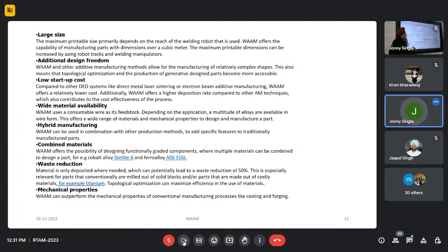But just imagine, analogous to this, you are going to now operate a facility with powder bed fusion. What you would be doing is, how do you control the two powders, Stellite powder and austenitic stainless steel 316L powder? In what proportion are they going to be fed into your laser beam? That is a bit difficult task. In this case, what we have to do is, we deposit 316L layers onto that, then use now Stellite 6.